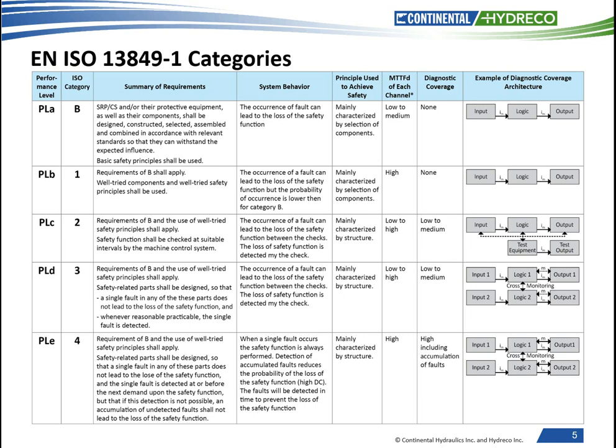In a Category 3, the restart function can reset if all monitored signals are corrected. The system should not permit itself to be reset if the monitoring system is not working. Diagnostic coverage can be low, medium, or high.